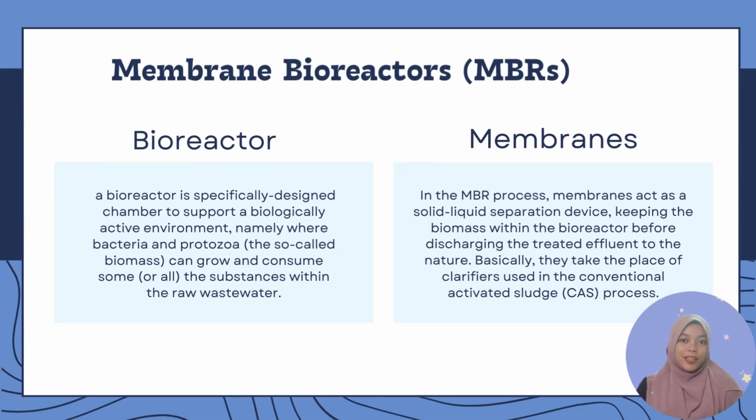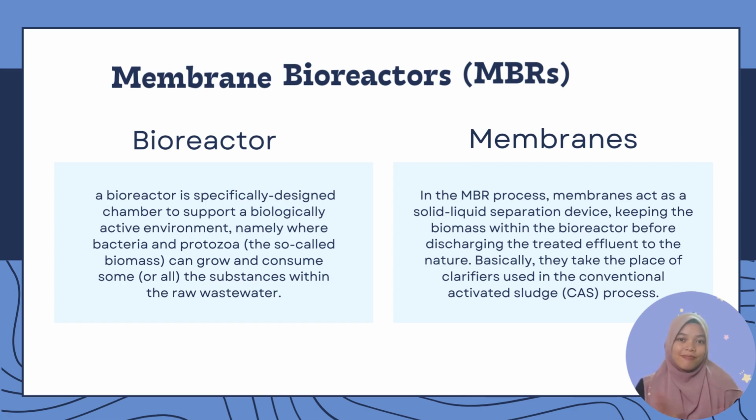In a membrane bioreactor, there is the word bioreactor. A bioreactor is a physically designed chamber to support a biologically active environment, where bacteria and protozoa can grow and consume some of the substances within the raw wastewater. Basically, they can be aerobic, anoxic, or anaerobic, depending on the presence or absence of oxygen and nitrite.